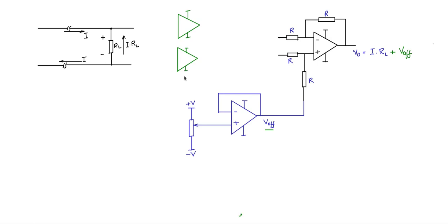Now note the polarities carefully, plus here on the top side, minus, and here minus on the top side, plus the bottom side. Okay, very important. So the plus I am going to give it to this in buffer mode, and the minus I will give it to here again in buffer mode. So high input impedance mode, so there is no loading on this at all. So absolutely almost zero current flows through here,